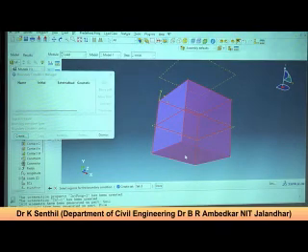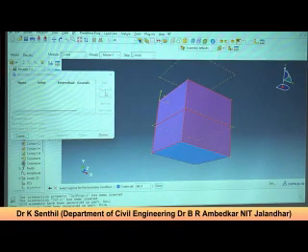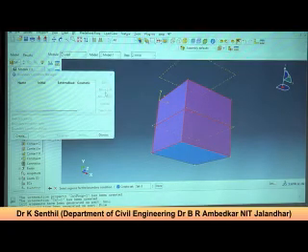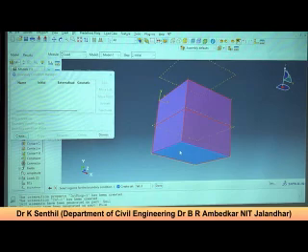Okay. So now I will not model this. I will not consider this. So that's why we will define two different conditions. The side of the soil will have different conditions, and the bottom will have different conditions. The side we will allow to go down, but we will not allow lateral displacement. That is the assumption we adopt. And at the bottom, I think we will keep it fully restrained. The soil will not go further, so no settlement. These are the conditions we can adopt.